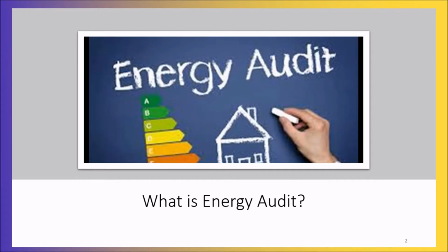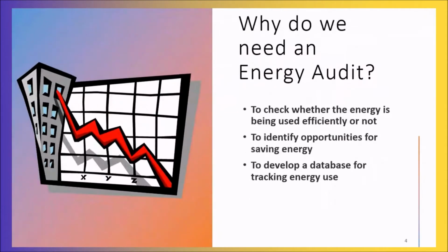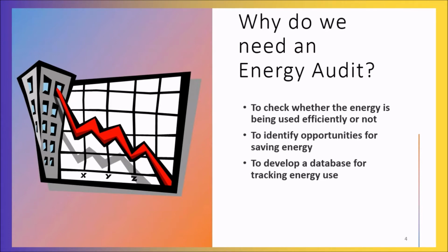What is an energy audit? An energy audit is a systematic investigation of energy use and energy consumption to identify opportunities for energy efficiency. Now, why do we need an energy audit? An energy audit enables us to check whether the energy is being used efficiently or not, to identify the opportunities for energy saving, and to develop a database for tracking the energy use.